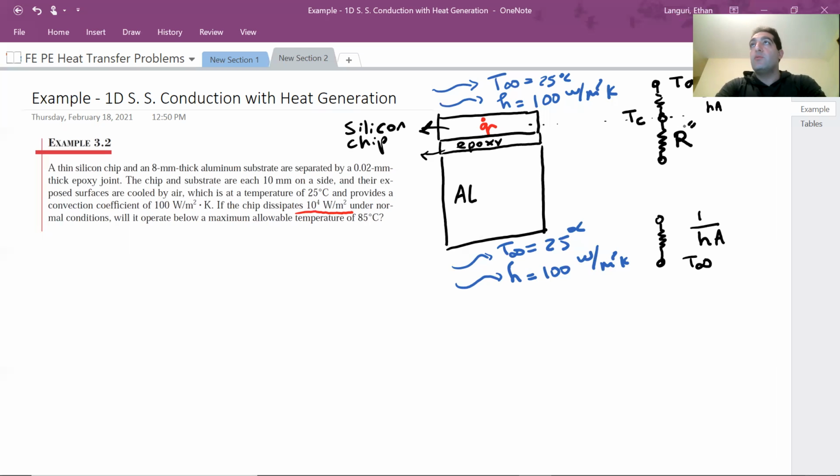Contact resistance arises because, in theory, you have a perfect contact with another substrate, but in reality there are micro gaps that still exist between them, which you either fill with epoxy or with an air gap, sandwiching a third material between the layers.